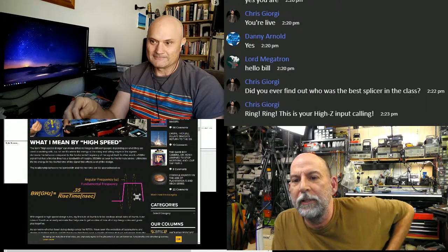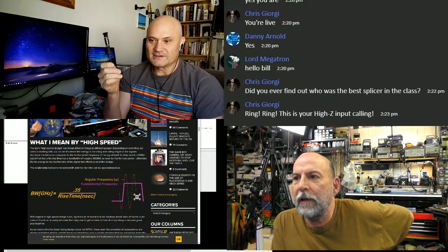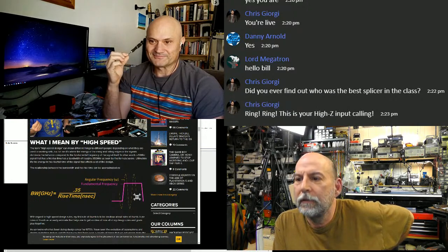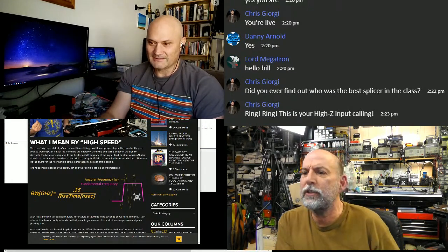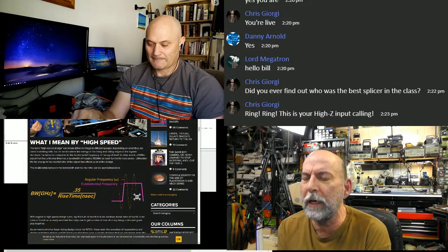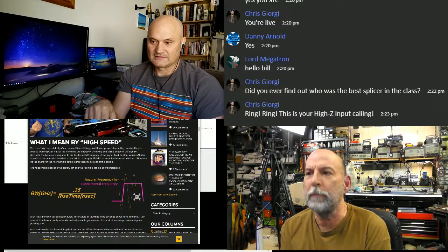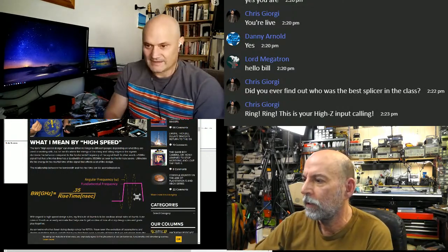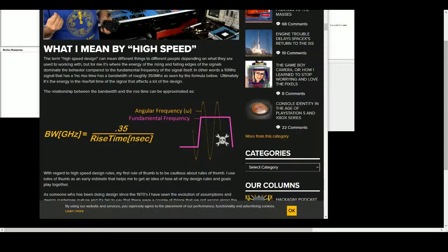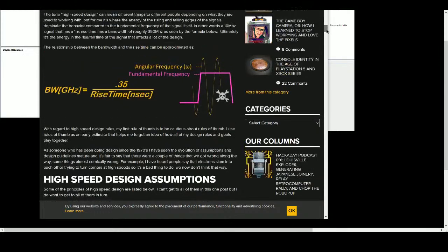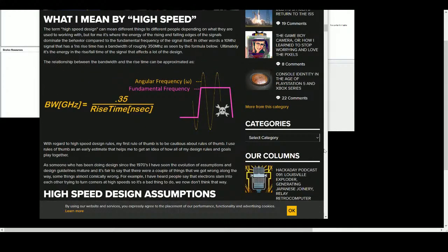So yeah, you were saying why we need the series now and the series versus parallel. Right. To stop reflection. So what do we mean when we say high speed though? We don't mean you can have a 1 megahertz signal and have a 50 megahertz component, right? That's right. And that's exactly what your article's talking about there in that quadrant. Because you've got high edge rates, you've got a lot of high frequency content in that. And anyone who's done Fourier analysis, at some point in engineering, you get into looking at the frequency content of every signal.